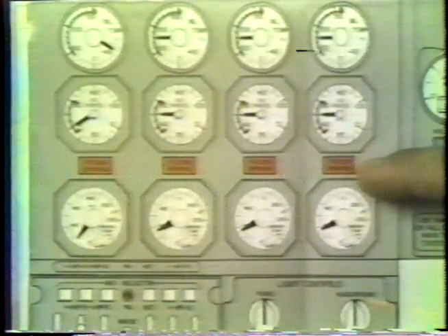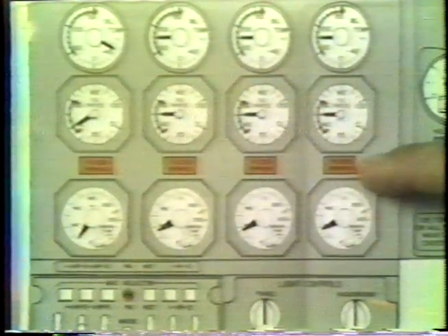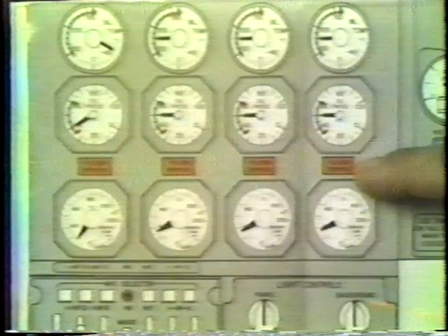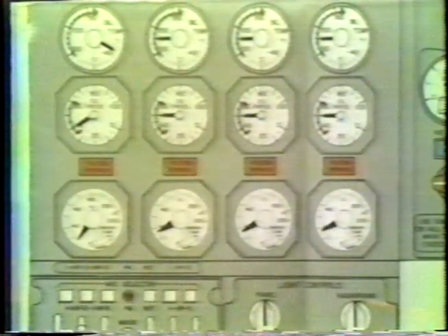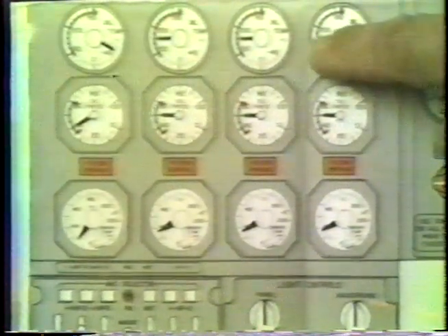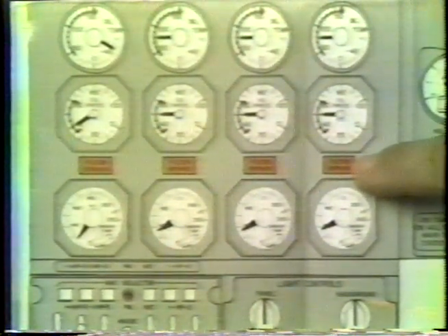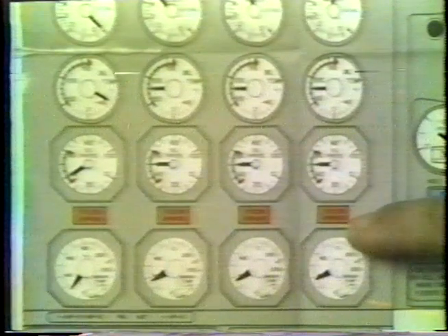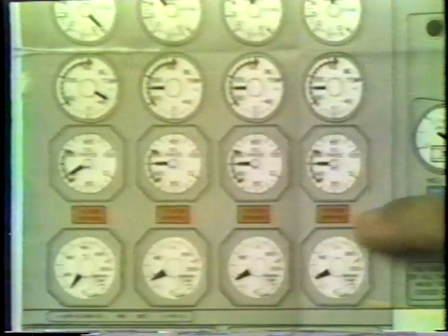However, on a very cold morning where the engine is cold soaked, the filter bypass light can come on, and this would be due to the difficulty of the oil getting through the filter. However, as long as the oil temperature is coming up, then it's permissible to have the filter bypass light on and continue operating the engine. Normally the taxi out time should be sufficient to warm up the oil and the filter bypass light goes out. If this does occur, engine operation can continue, however a logbook write-up should be made.